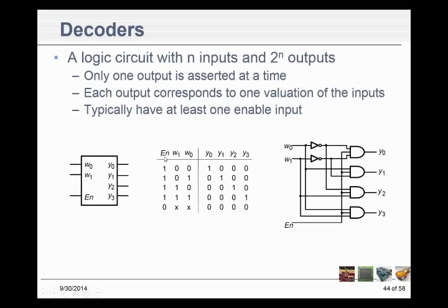We got an enable signal. That's what that stands for. When enable's high, and it could be a not enable, meaning when enable's low, it would have a bubble at the beginning if that were true. And that would say when it's low, this thing is turned on. If enable's 1, it's turned off. Well, this one, no bubble, no line over it, no not before it. So it says this chip is turned on when the enable bit is 1. Otherwise, it's turned off. And that's why it's saying here, when it's turned off, it doesn't matter what the two inputs are. The outputs are always going to be 0 when this thing is disabled.